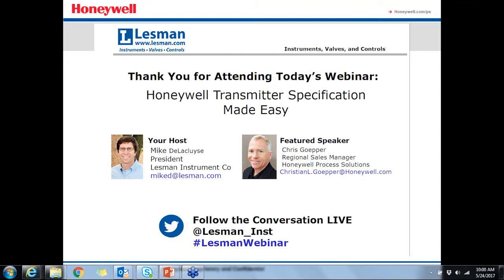In our 45-minute session, we'll cover writing some complete specifications for smart transmitters, some model selection and chemical compatibility information, step-by-step selection of options critical to your design, some online tools for model number validation and automatic specification generation, and at the end, we'll have a question and answer session.